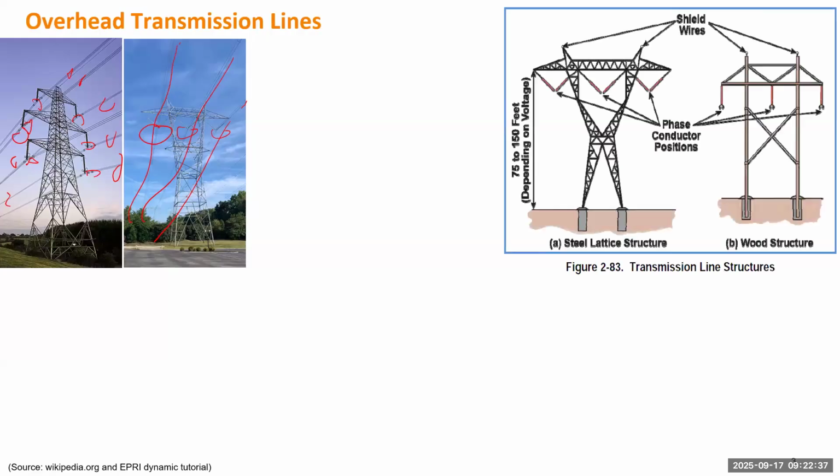The top wires are called the shield wires. They are not delivering electricity over the conductor. They provide a circuit if you have any fault, which helps to protect the transmission line locally. If there's any grounding fault, the shield wire will be functioning. But in most conditions, you only have those 3 transmission lines.